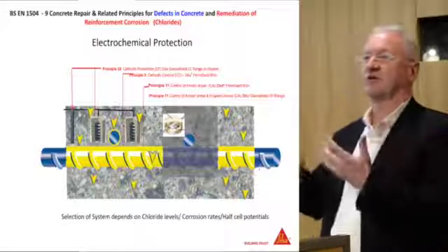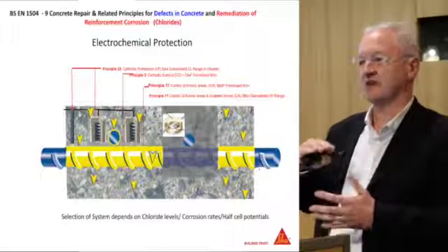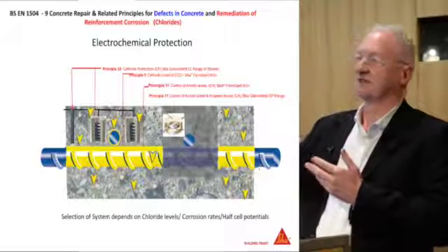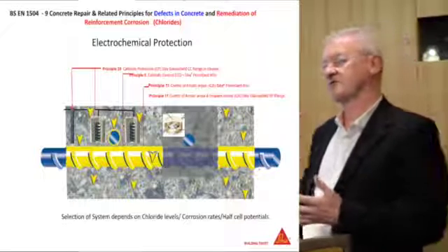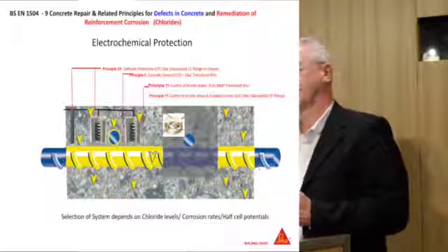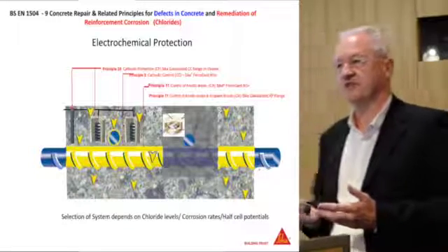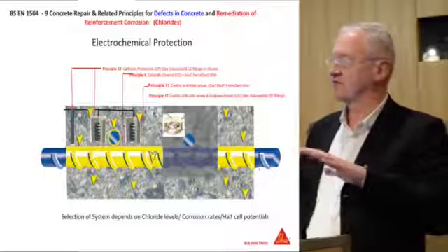an inhibitor all around. But then when you start to look at the car park decks, which generally will have chlorides on, you'll have chloride depths and concentrations at various levels on the decks. And generally on the first 2 to 3 levels, they're very concentrated. Your corrosion rates will be quite high, so you'd then possibly look at some sort of cathodic protection system